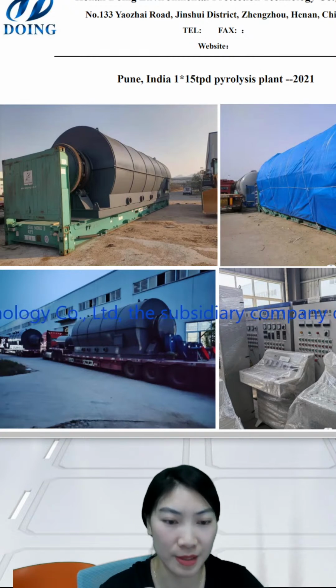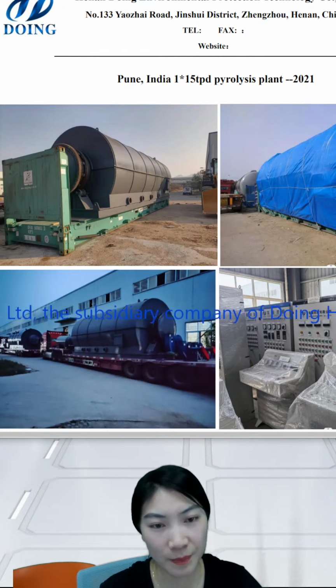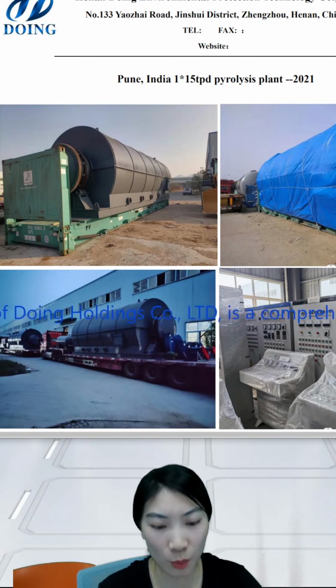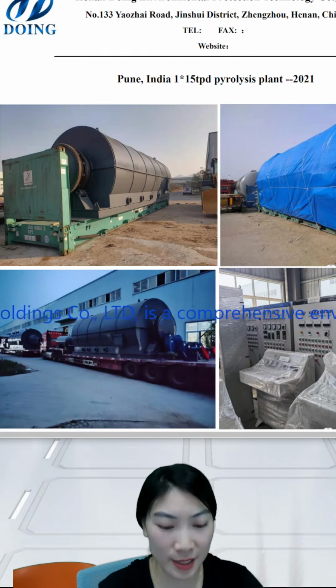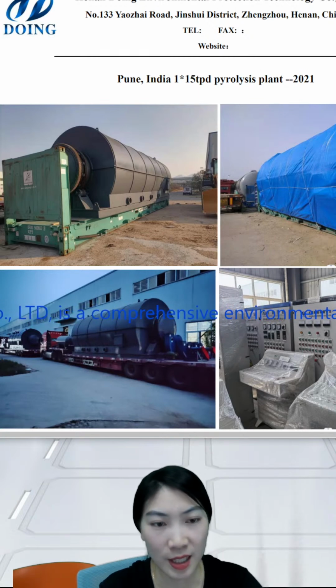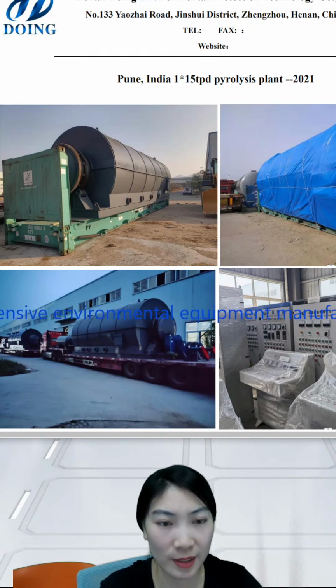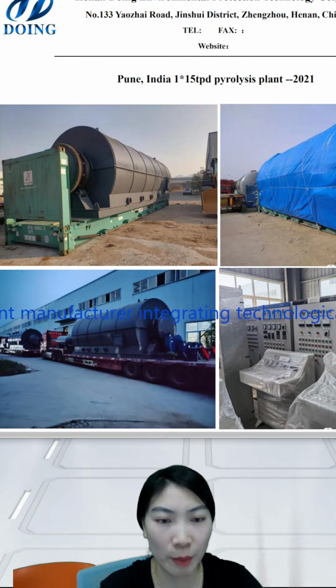Normally we have 3 types of pyrolysis plant, but the raw material is a little different. If you use whole tires or plastic waste, you can consider a batch pyrolysis plant. It's easier to load and feed the raw material into the reactor and operate. For the semi-continuous, the main raw materials we suggest are rubber powder, mixed plastic or oil sludge, but the best choice is oil sludge.